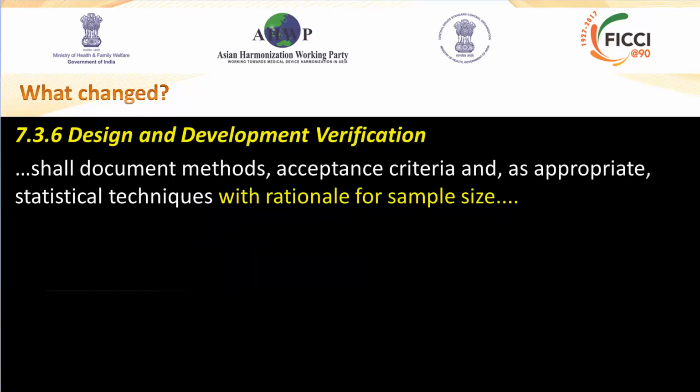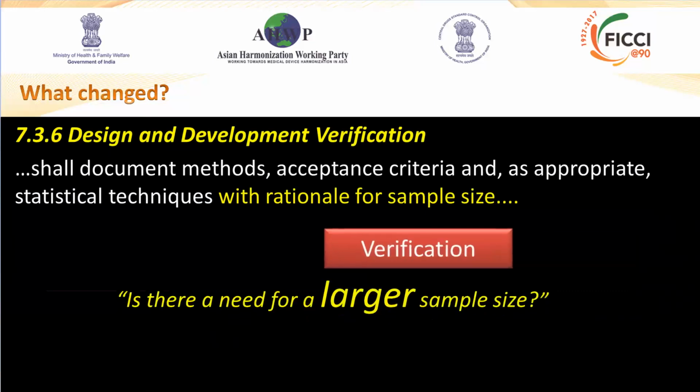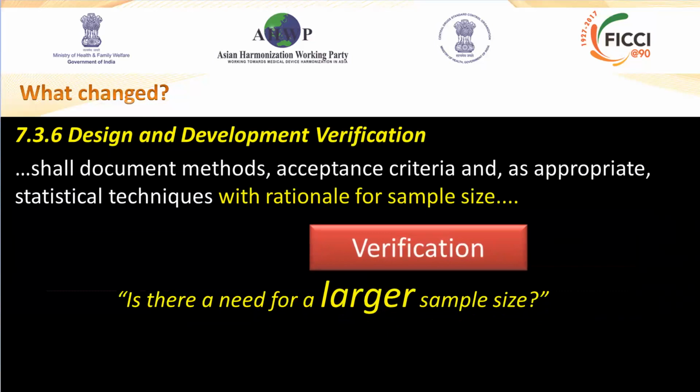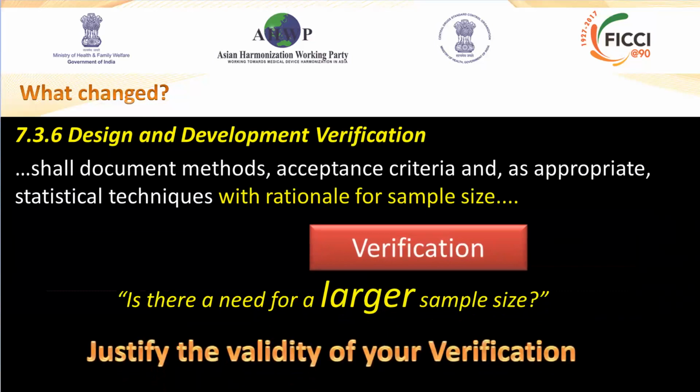Design and development verification shall document methods, acceptance criteria, and as appropriate statistical techniques with rationale for sample size. We're seeing a lot more interest in the sample sizes that manufacturers choose when they do a verification and validation activity. They want to know if there's a need for a larger sample size. You should be able to justify that, and that could be done based on the risk related to the particular aspect of the device that's being verified.